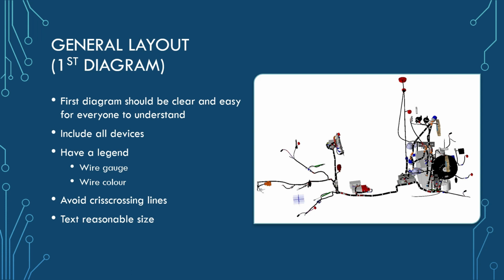And if they did want to help, they would at least know that, oh, if we want to connect a wheel speed sensor in the back rear, it needs power and ground along this line here going through the firewall, and it's going to this input into the ECU, essentially like that. Usually this diagram is blown up to basically poster size so that everyone can read it fine, because usually the text on the ECU is a little bit smaller, but still a reasonable size. Everyone can read it when it's blown up to a bigger size.